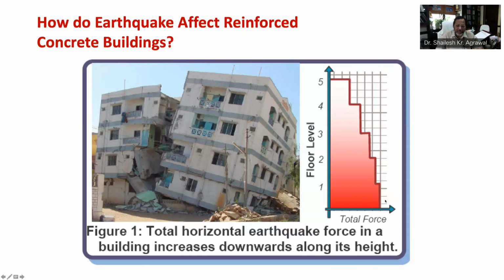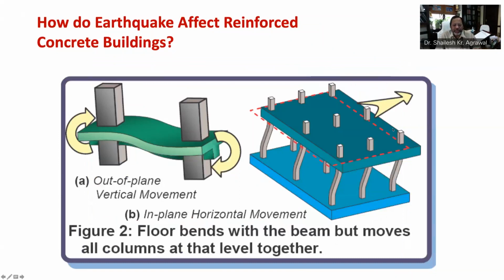Therefore, always remember, lower story columns experience higher forces and shall be designed to be stronger than those in stories above.